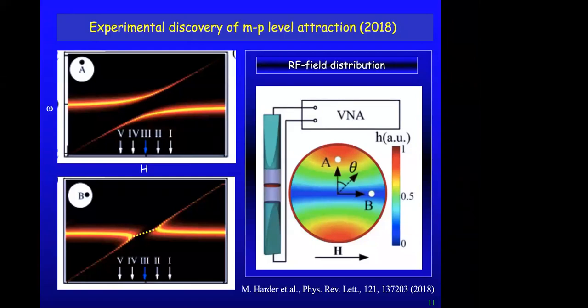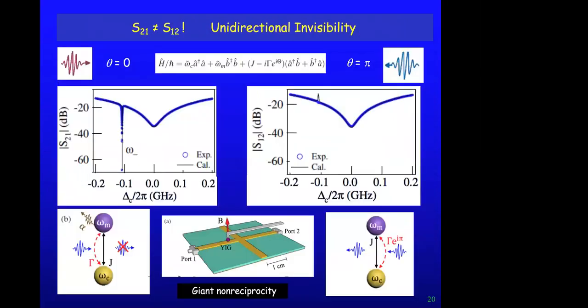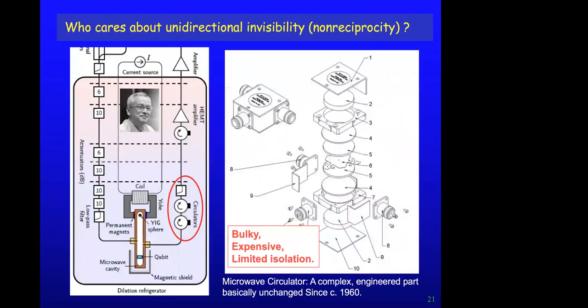Hello, thank you very much for the nice talk. I have a question about the newly proposed model of circulator. So in principle, any existing circulator can be tuned to one particular frequency and have virtually infinite isolation. The reason they make it more broadband is why the isolation goes lower. But another important parameter for a circulator is actually transmission loss.